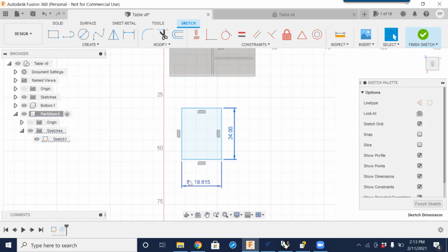And that's what this FX is referring to. And if you just notice, when you hover your mouse over top of there, it gives us that formula. So it is the length_y divided by 2, subtracting the material thickness and subtracting another dimension of 1.01 inches, which is the offset here. So what are those made up variables? Those made up variables are what I just deleted the 1, and we're going to change this 24 to a variable.